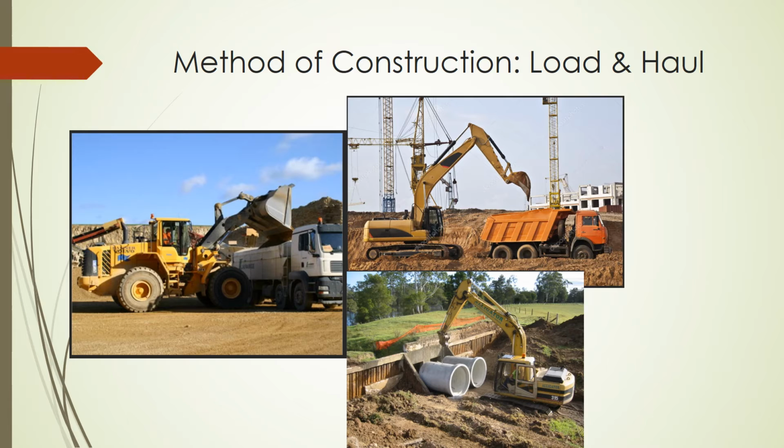An advantage with this construction method is your machinery is incredibly versatile. You can use your tippers for moving stuff, moving plant around site, moving everything else around site. You can use your excavators for low intensity craneage if you require. Thus, you can see this excavator in the bottom is being used to build and install some culverts behind a pile wall, which is incredibly helpful in basically keeping your